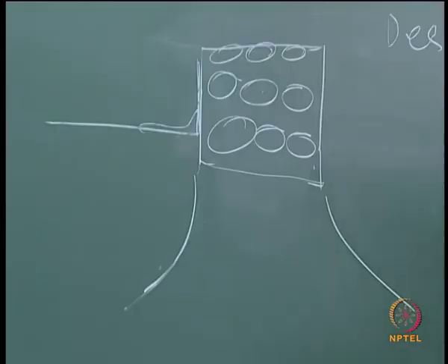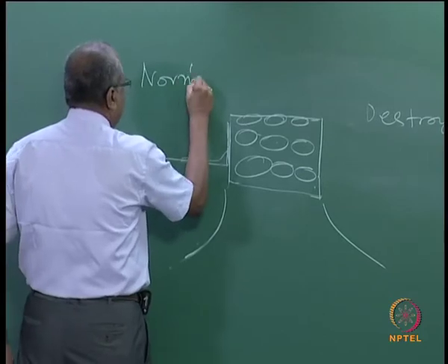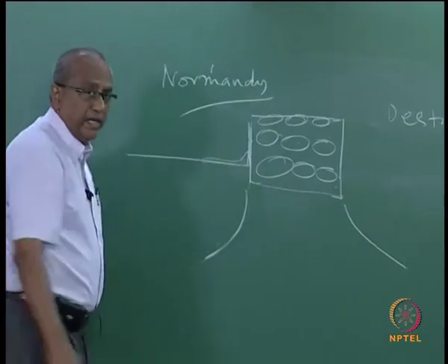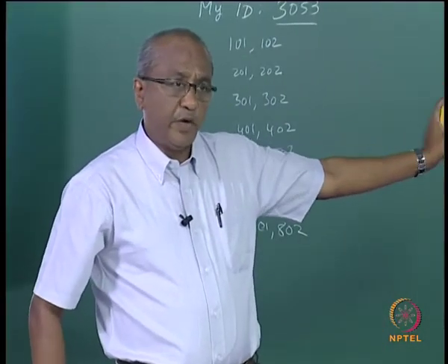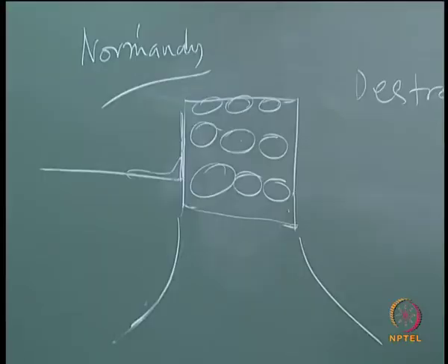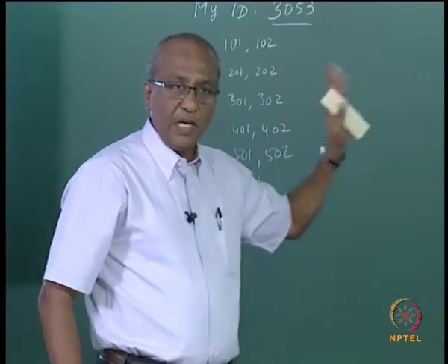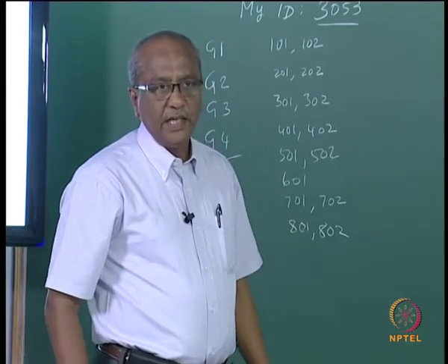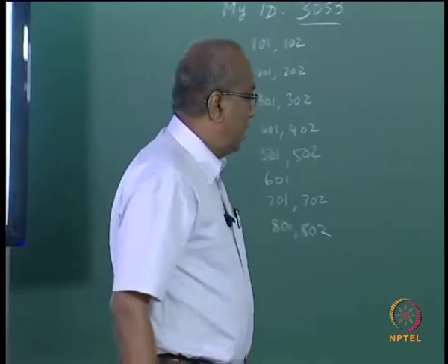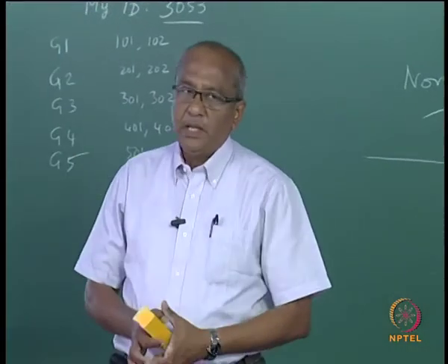So these are all some of the concepts, and a lot of effort has gone into making this floating breakwater. The concept of floating breakwater started as early as the 1940s, during the World War, during the invasion of Normandy. That is the time when the concept of floating breakwater came into existence. Floating breakwater has its own advantages, but it certainly has certain disadvantages. Particularly it is not that effective in attenuating long period waves, okay.